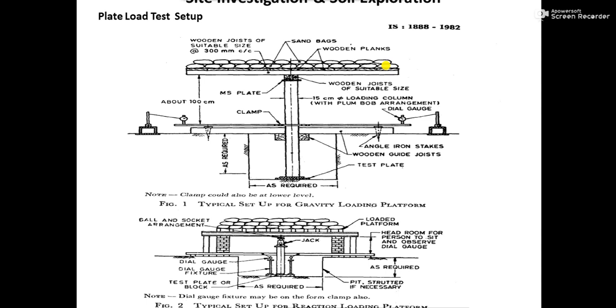So as and when you put the sandbags, before that you take a weight of that. So gradually if you go on adding the sandbags on top of that platform, what will happen? That will create some incremental loading which will be transferred through this loading column to the plate at the bottom. And where is the plate?